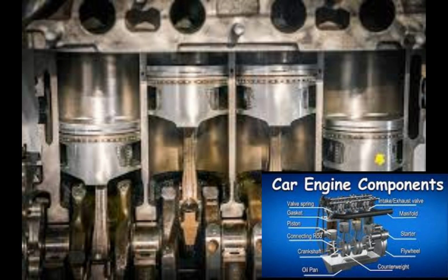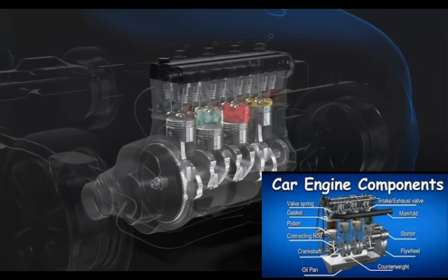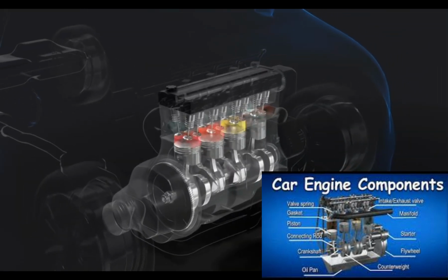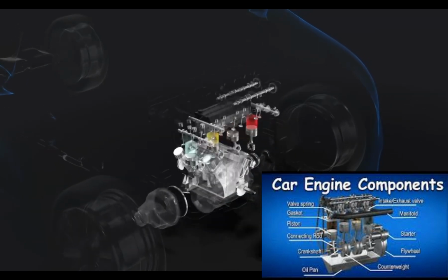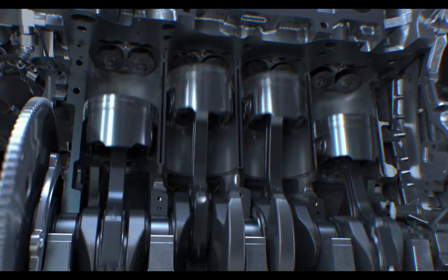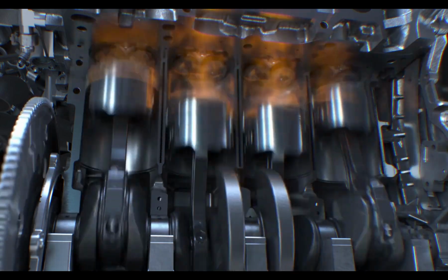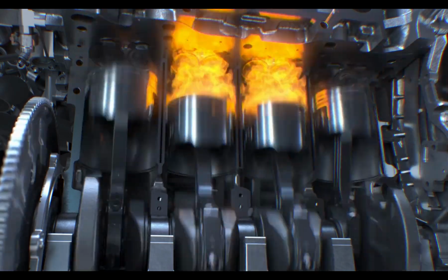1.1 Cylinder block and crankshaft, connecting rod mechanism. The engine block is made up of many components, but the key parts responsible for movement include the cylinder. This is where the combustion process takes place, generating power. An engine can have between 2 to 12 cylinders arranged in different configurations such as inline (I), V-shaped (V), or opposed (boxer). The piston moves up and down inside the cylinder to complete the 4 strokes: intake, compression, power, and exhaust.